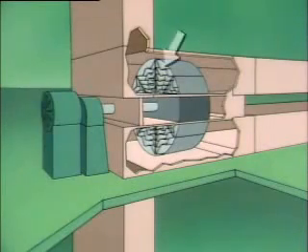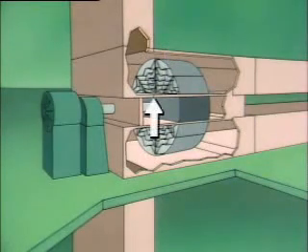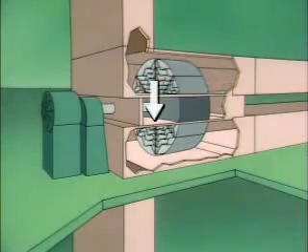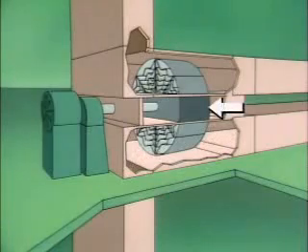This one consists of a series of heating surfaces or elements which are connected to a motor-driven shaft. The top half of this heater is in ductwork that routes hot combustion gases from the boiler through the air heater and on to the stack. The bottom half is in ductwork that directs incoming air through the heater and on to the boiler. A seal prevents hot combustion gases from mixing with the air flowing to the boiler.